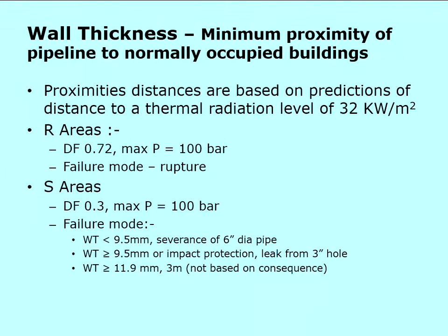And the criteria they applied was you're going to hit the pipeline with a sharp machine tooth, and if you produce a dent of 0.2 inches depth in different materials, then that's going to give you a limit on wall thickness. And basically wall thickness is here, that's the 9.5 and that's the 11.9, and they were related to the damage that could be caused by typical construction machinery.